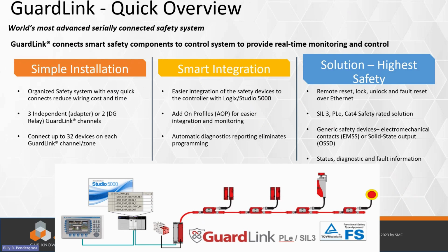GuardLink connects safety components into a smart safety topology. This allows for simple installation with quick connects. Smart integration with devices linked with Studio 5000 with automatic diagnostics reporting eliminates programming. And this system is rated the highest safety solution of SIL 3 or PLe. Remember, those two are different.